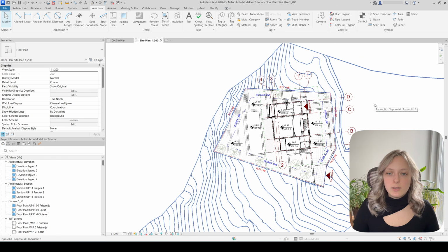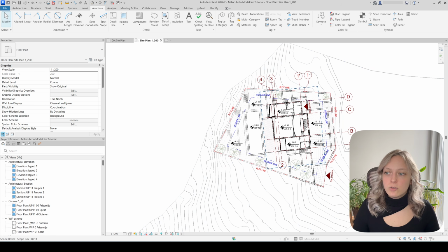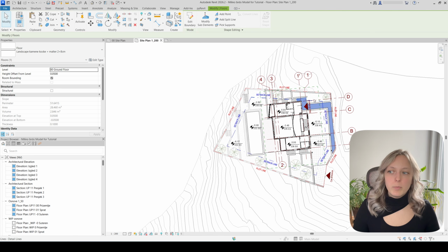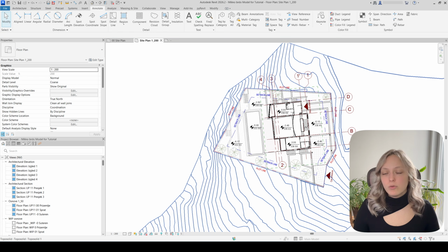Of course, it is important to check your area regulations to see what falls under the important spots. Usually it is some kind of entrance, ground floor, some of these elevation changes. Obviously, for project like this, I have to have the spot elevation everywhere here. Each of these different layers have to have elevations, each of these different paths, these walkways, but of course we don't have time for that because this lesson is already too long as it is.